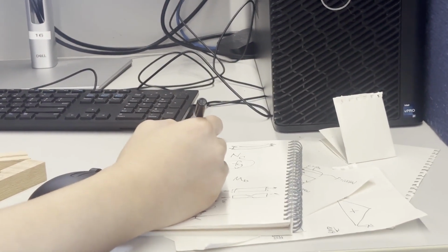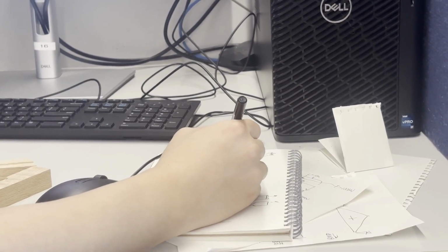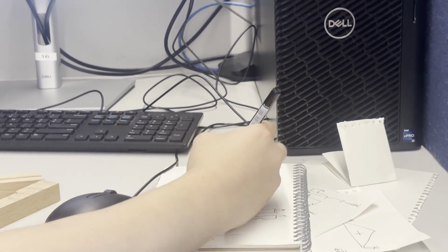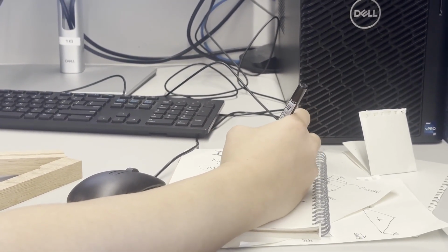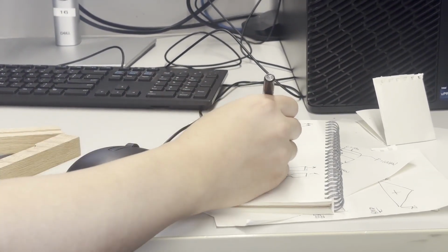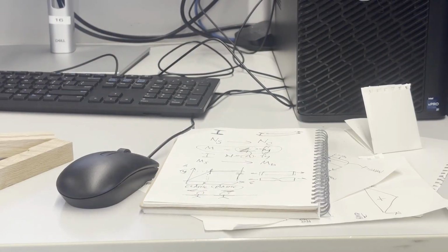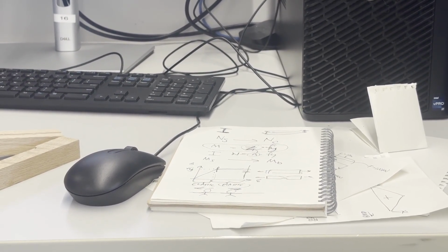The moment is this thing called the elastic section modulus, Z, multiplied by the yield strength, right? So you can see similarities with how you've been doing it for tension and compression, because it'd be area multiplied by that. The analogy is, your elastic section modulus is basically your area but in bending.